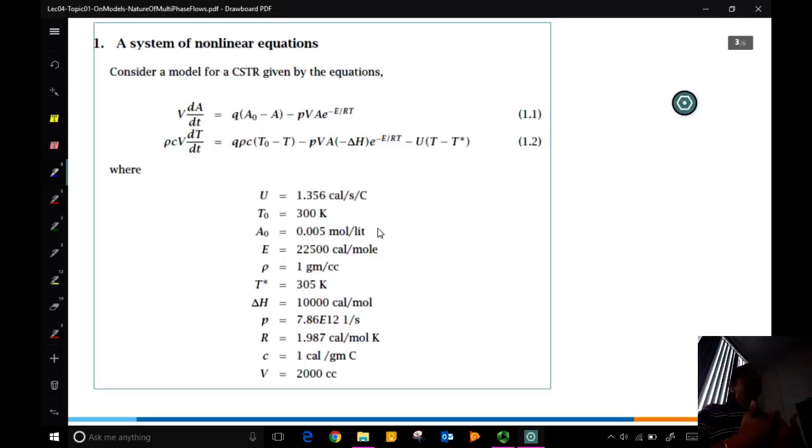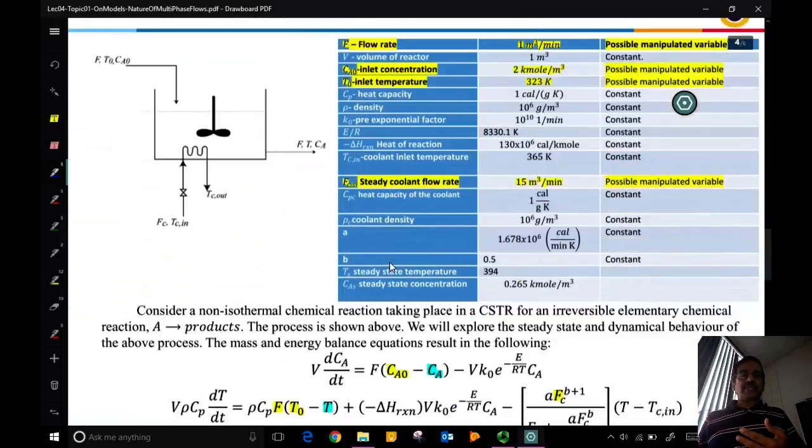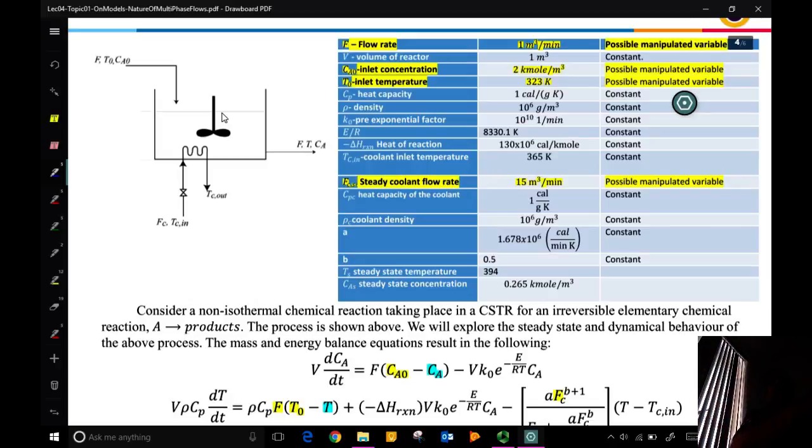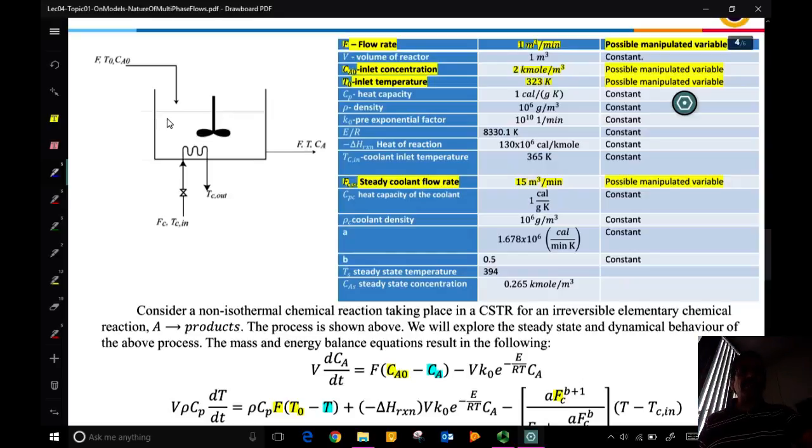Essentially, it comes from a mass and energy balance on... actually, here you have the figure. So you have a reactor which is a cylindrical vessel with some liquid in there, and you have a stirrer to keep it homogeneously mixed. So there are no spatial variations. When you have spatial variations, we need to learn how to solve the Navier-Stokes equation to look at velocity fields, etc. Here, the CSTR assumption says whether I sample the composition from somewhere here or somewhere there, composition is uniform, same. And it is the same as the exit composition.